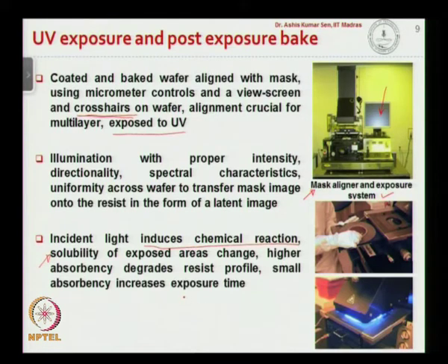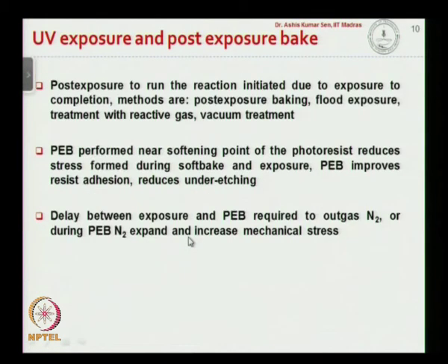That is going to happen if the absorbency of the photoresist is more, whereas if the absorbency is less, then the exposure time has to be more. So you need to expose it for a longer time for the photochemical reaction to happen in the case of a photoresist with small absorbency. Once we do the UV exposure, as I said, a photochemical reaction is initiated, and you can in fact see the pattern getting transferred.